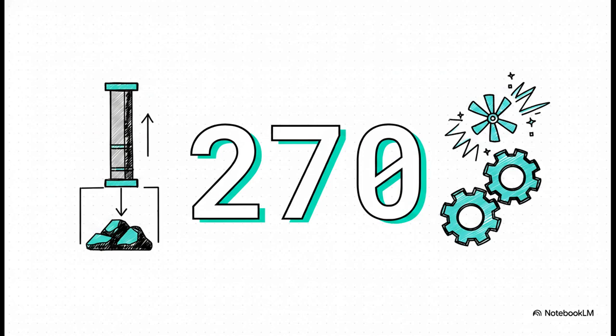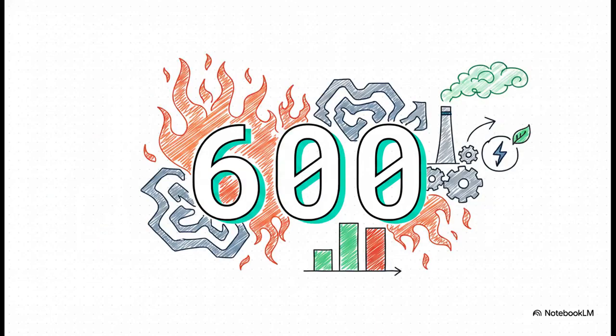We are leaping from 170 all the way up to 270 kilograms per square centimeter absolute pressure. I mean, that's huge. But this intense pressurization is the absolute key. It's what allows us to extract significantly more work and energy out of the exact same amount of coal. And right alongside that intense pressure, we have the temperature, 600 degrees Celsius. We are now targeting 600 degrees for both the main steam and the reheat steam.